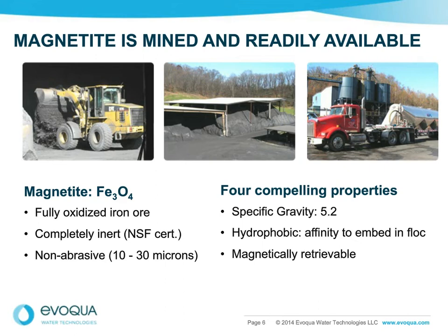As I said, it's mined all over the world. Its source is readily available. And obviously you're adding weight to solids, and when you dispose, because you're pulling solids out of your treated water, you need to dispose of those solids. You don't want to increase the weight of those solids and increase the cost of disposal. So we go through a process of recovering the magnetite and putting it back in the process again.